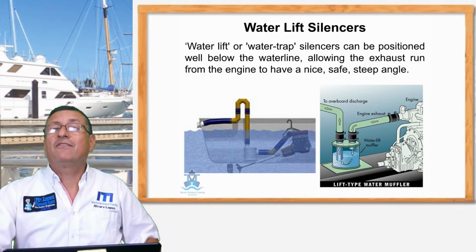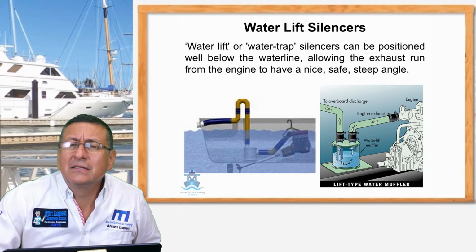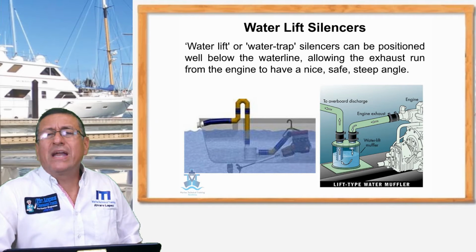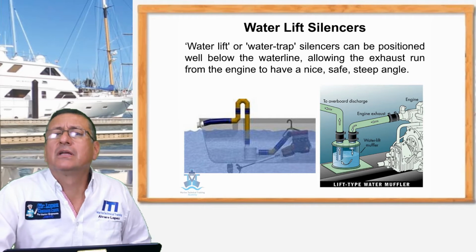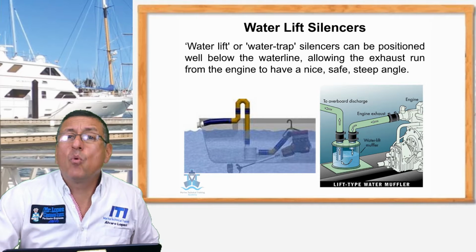Follow the lines. Now I want you to verify where the muffler is located. Where is the muffler located? And where are the input and the output on the muffler? I want you to verify if that engine has a water separator.